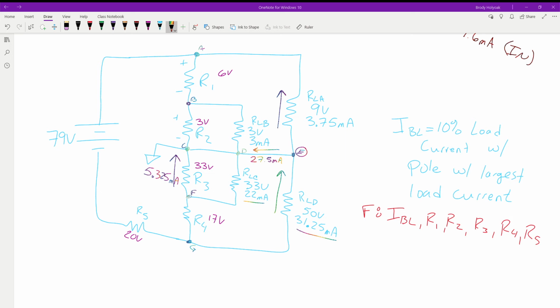Dylan. There it is. Okay, current at node D. Yep. We have 3 going out. So we add 1, 2, 27.5. We get 49.5. Okay. Minus 3. We're left with a surplus of 46.5. So 46.5 going to the left. Yep, heading out of that node.